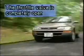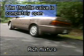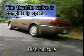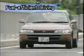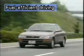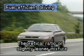A greater ratio of fuel to air is necessary to obtain the needed power when climbing hills, or other times when the throttle valve is opened wide. The theoretical air-fuel ratio, or a slightly leaner mixture, is needed when driving on straight even roads at constant speeds.